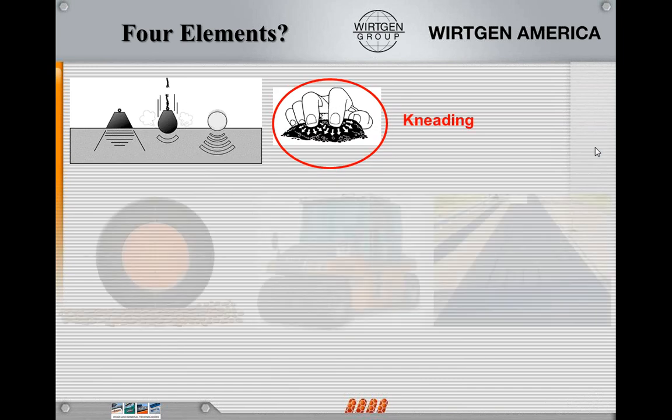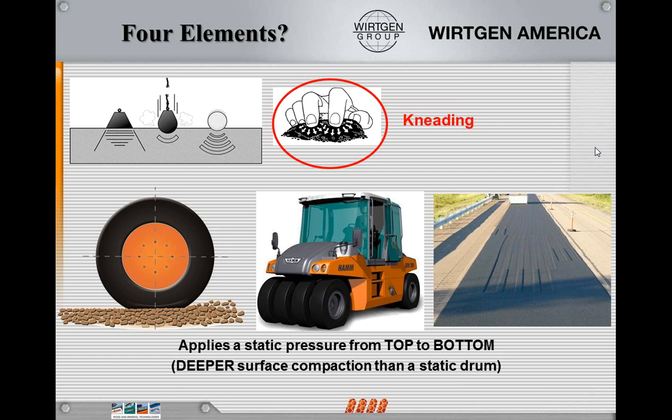Now, on the asphalt side, there are a couple other advantages too. The rubber tire roller really compacts from the bottom up by kneading that material in between the tires, almost walking it out to the top, kind of like what a pad foot roller would do on the soil side. It also helps pull the fines to the surface to help seal the surface, which reduces the cracking I talked about before, so we're not inducing any kind of moisture in the material.